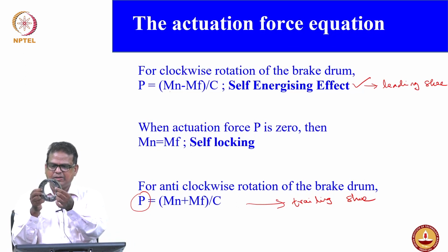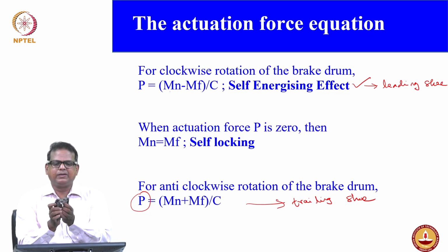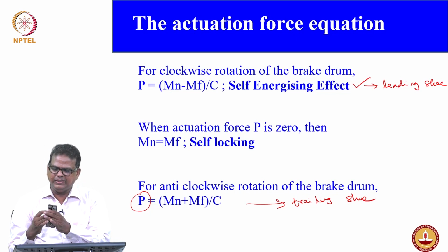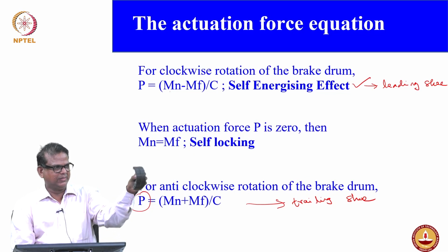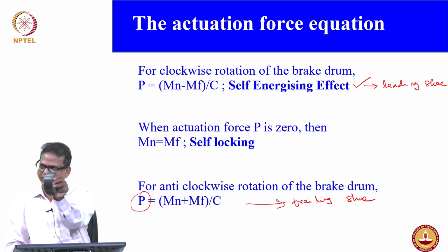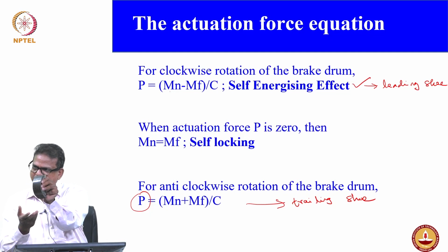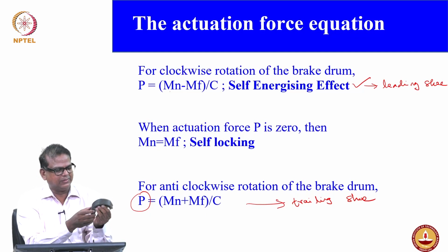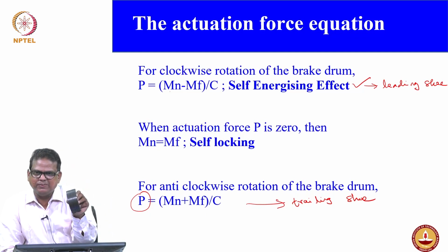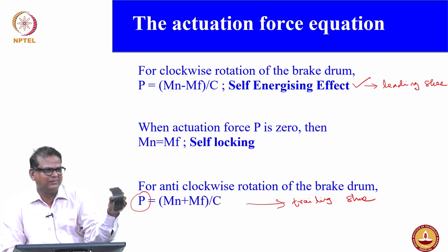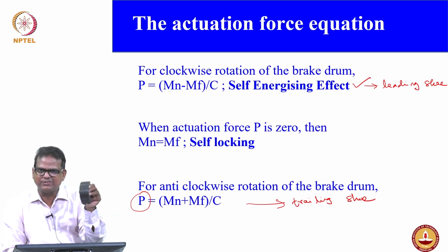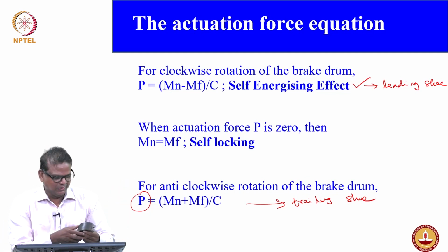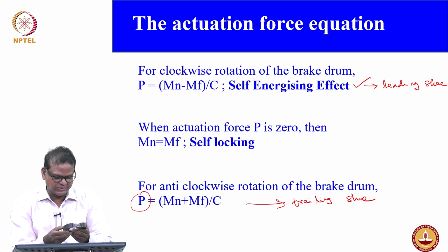This is actually a drum brake system. Can you tell me, are both leading and trailing, or leading and leading? If you look at this arrangement, it is leading and leading because there is no short length of brake lining. This is the brake lining, and in fact this is a Honda Activa two-wheeler brake shoe. It is from my vehicle. Maybe I can circulate it, you can see it at a later stage.